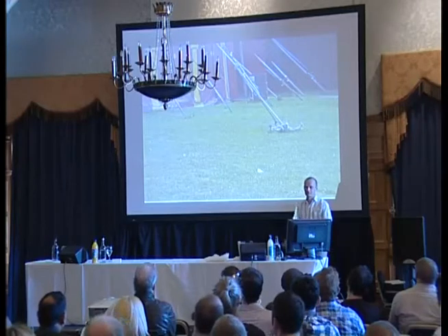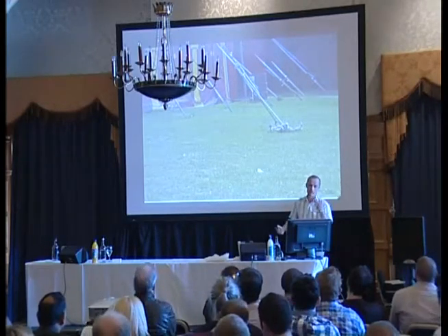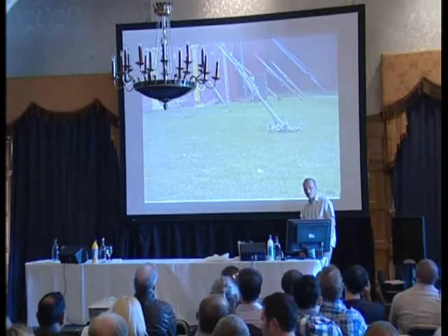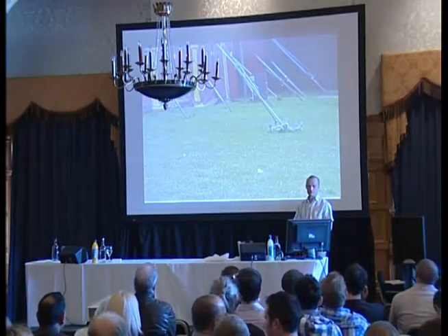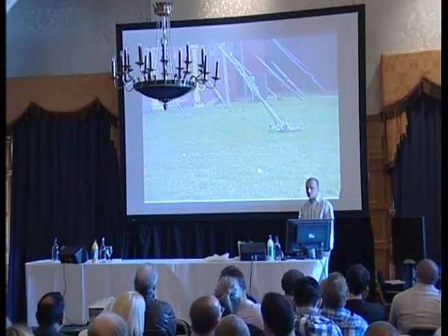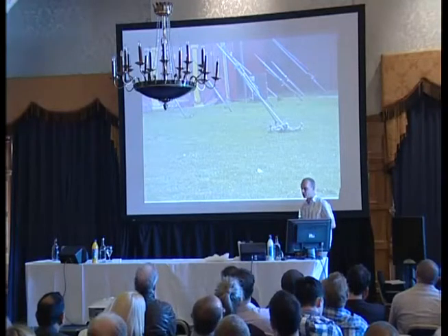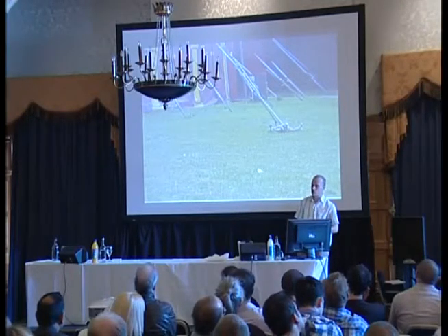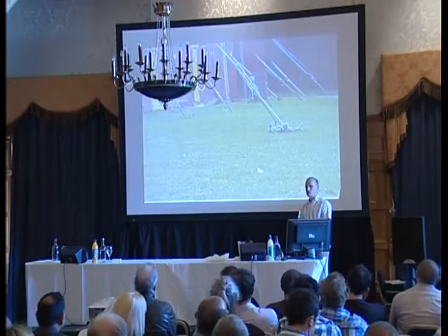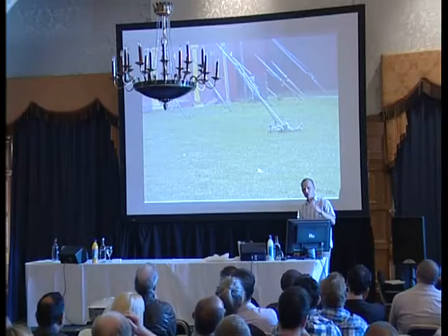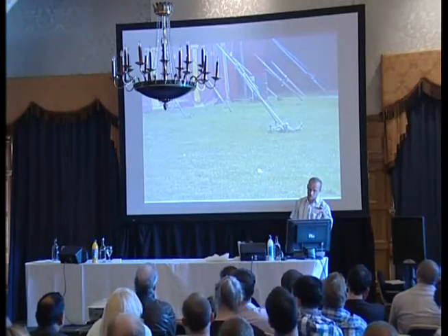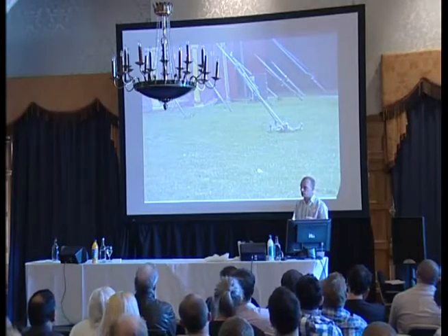The ground itself, exactly. We're putting that in nice, thick clay. It's probably quite happy, because thick clay tends to be gungy and holds those stakes in. If those are just straight driven pins, which those particular ones are, that's fine. But if it's a gravelly surface and they've had to bash it in and wiggle it down, that's probably got no tension at all. So ensuring that your ground conditions are good for your stakes is absolutely vital.